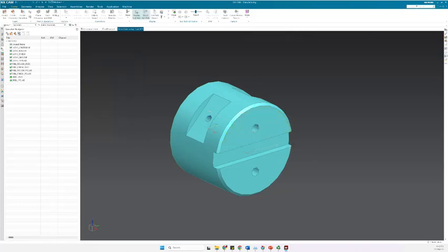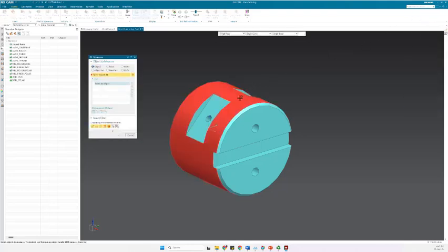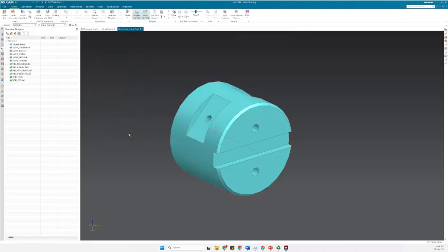And then if I just wanted to measure the diameter, again, I'll show it here. And then if I just click here, I can see that the radius is 21. So a diameter of 42 is the one that we are going to use. So now these are the values that help me in defining the raw stock material.